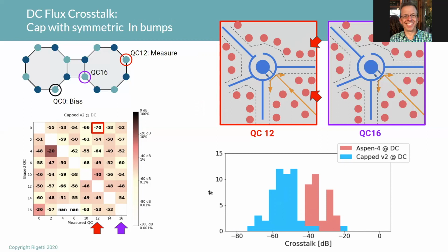So what we're seeing here is both the concept that using a cap with indium bumps can reduce flux crosstalk, but that part of the mechanism here is that we are moving the return currents from these flux biases, the currents that are flowing to ground, off of the ground plane on the QUIC that's circulating past every other qubit and onto the cap ground plane.